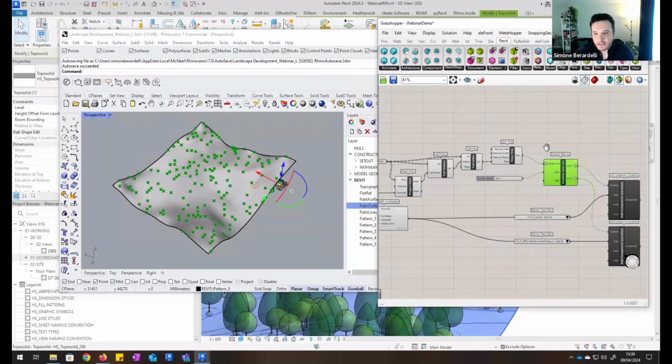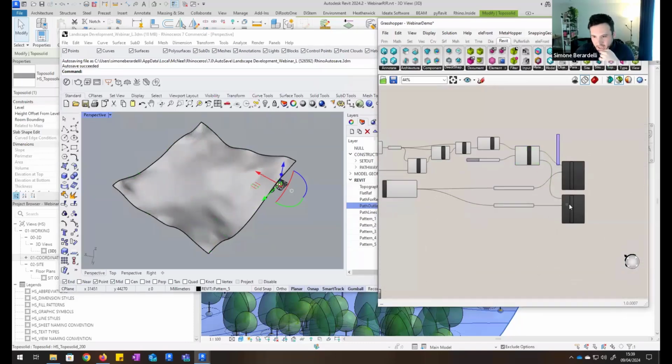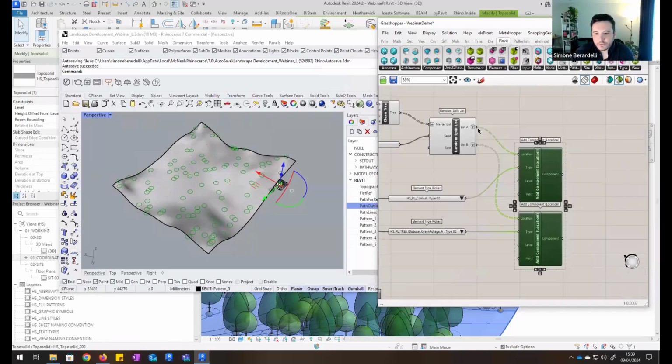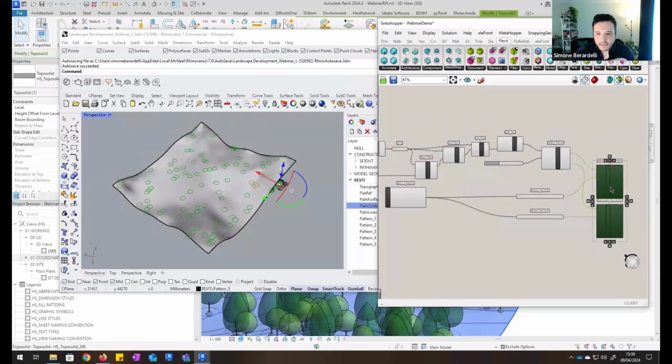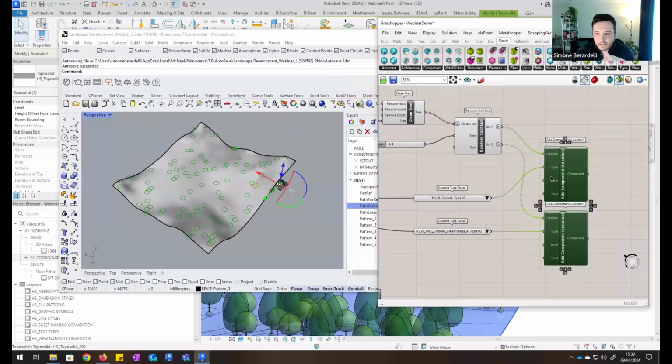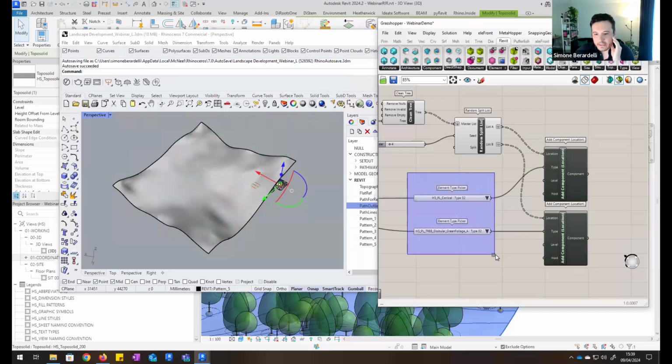And then at the beginning and at the end here, I have my lovely Rhino Inside node. So until here, this is all a Grasshopper script. And these two are the nodes that are baking, that are actually placing my family here. There are 2 trees and they are going according to these points that you see here.